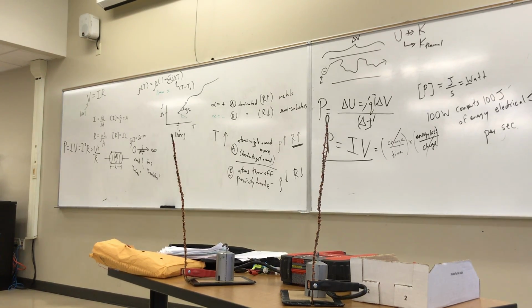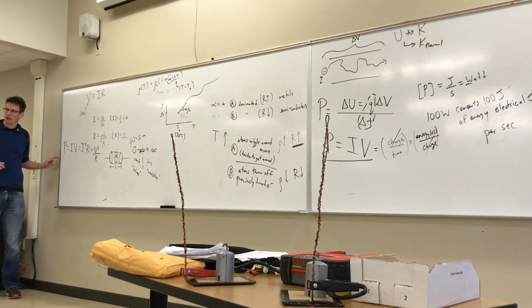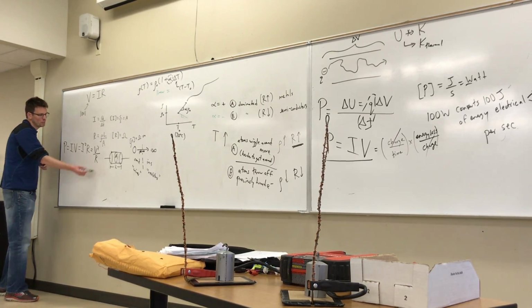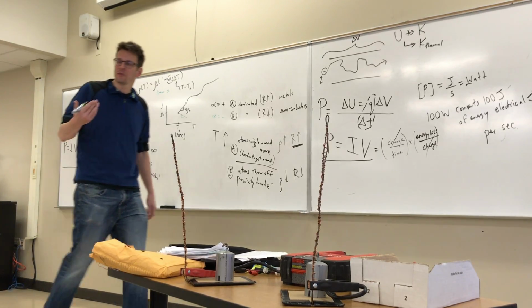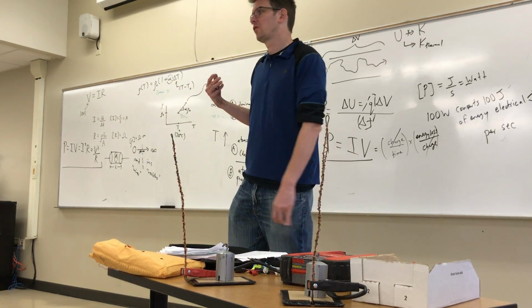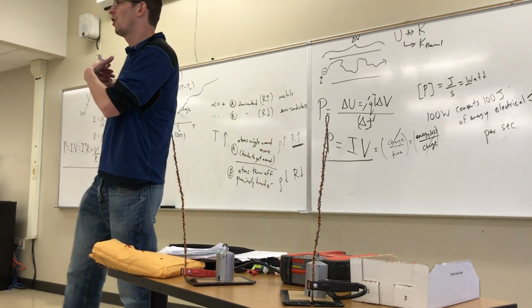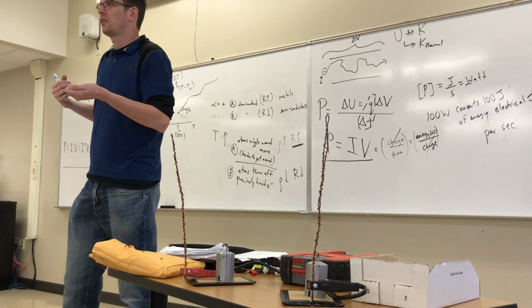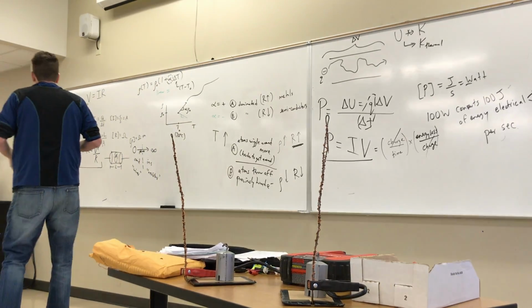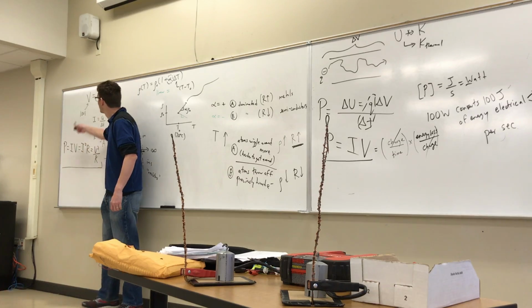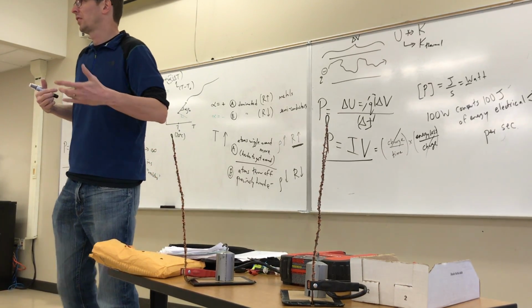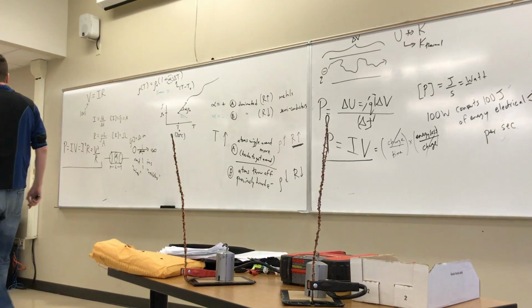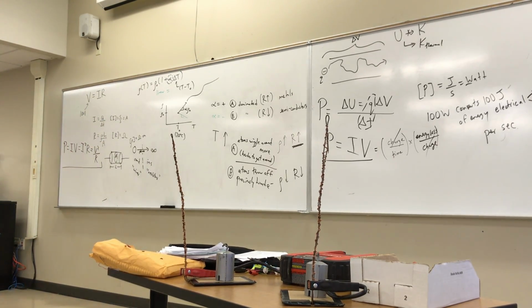Now you might question, why would we want to have three forms sitting around? There's going to be good reason when we move into more complicated circuits to have choices. We'll find that some of those power laws are really helpful for some types of circuits, and other ones are helpful for other circuits, so it's nice to have them ready-made so we can grab any one of the three that's convenient. They're all equivalent, they all come from this, but I'm subbing in Ohm's law to get the various different options, okay?